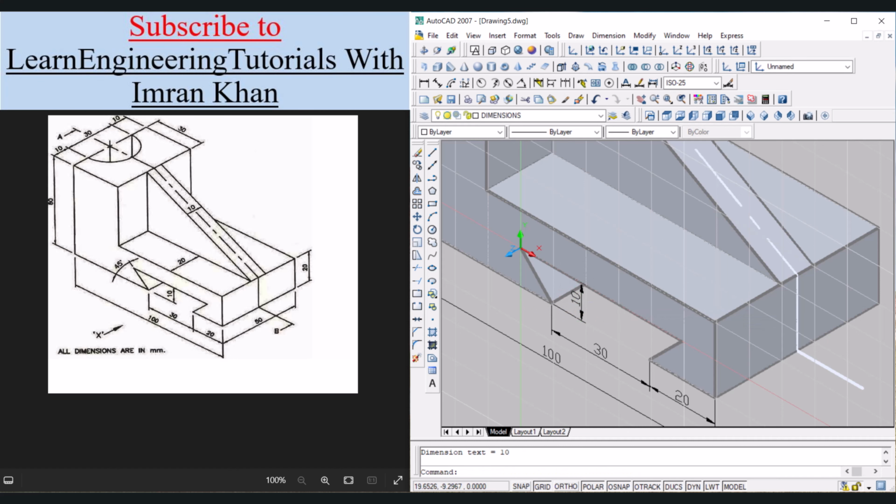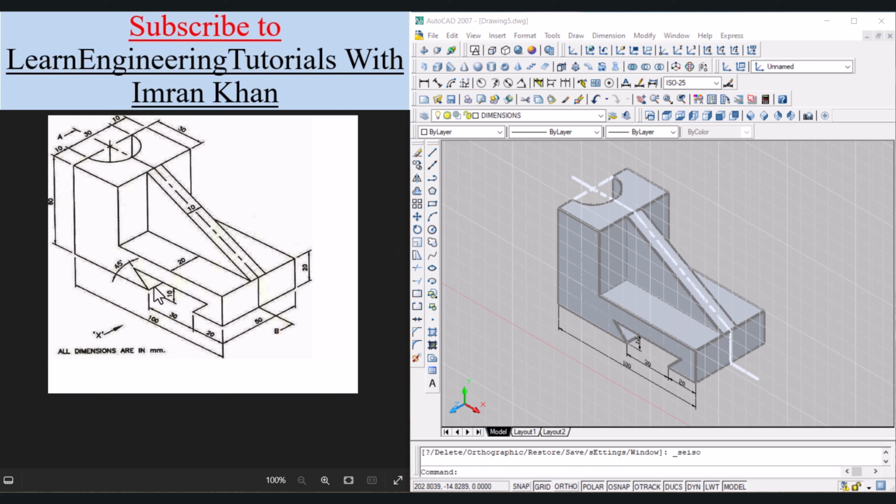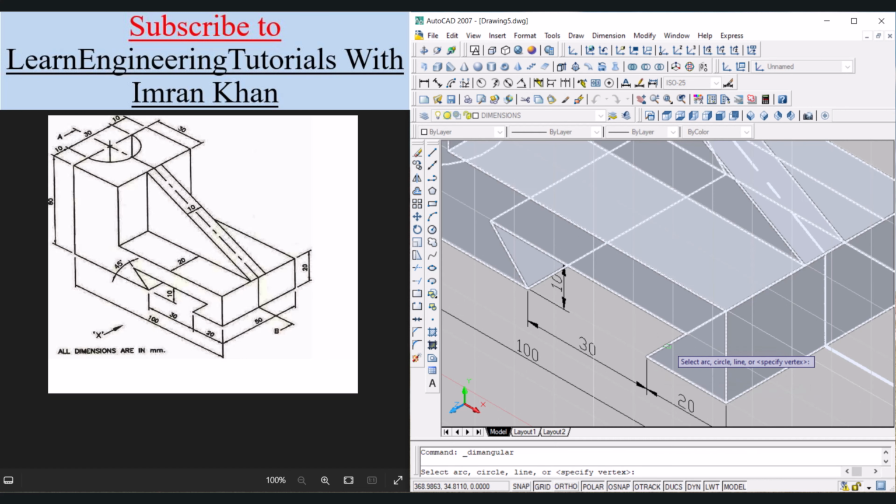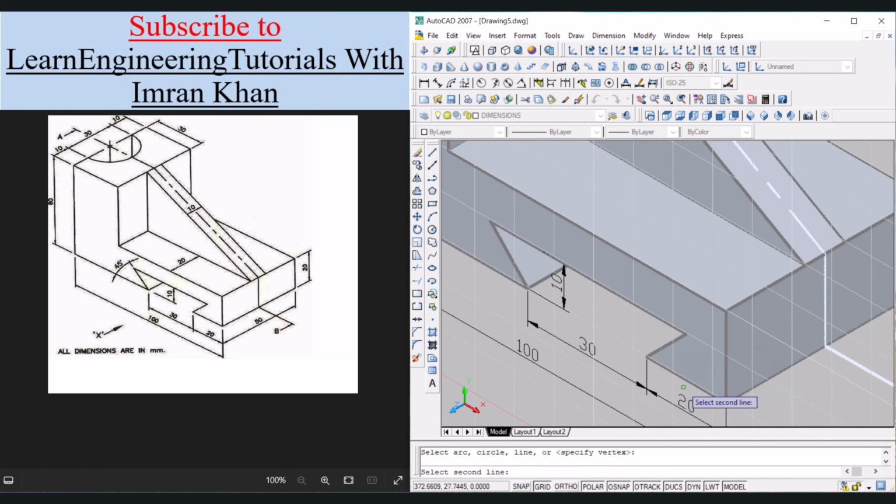Now we have to add this angle. In the diagram the angle is shown over here. We can also show the angle over this area. So for that click on this angular icon, click on this inclined line, click on this horizontal line, and now move the cursor away and click.